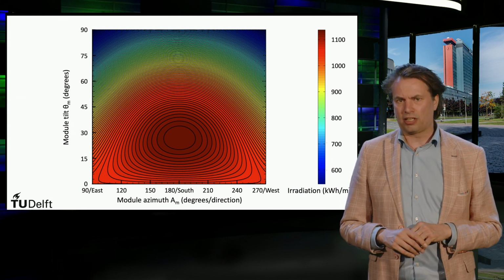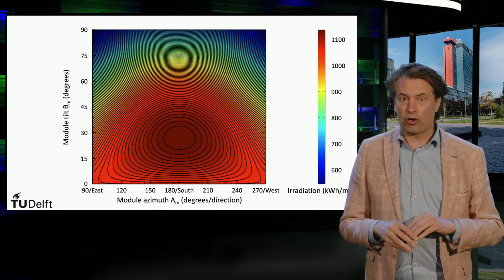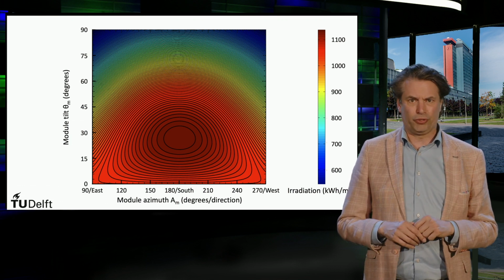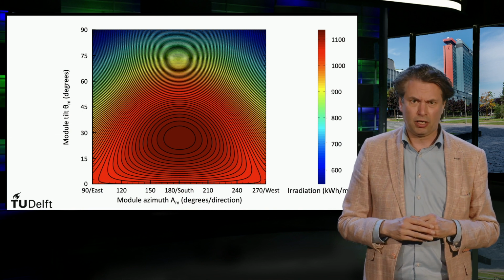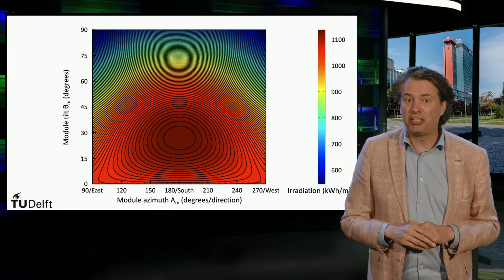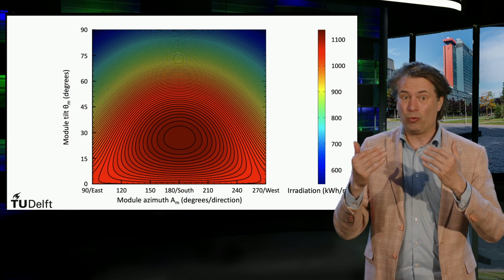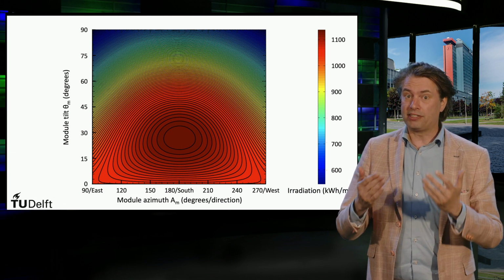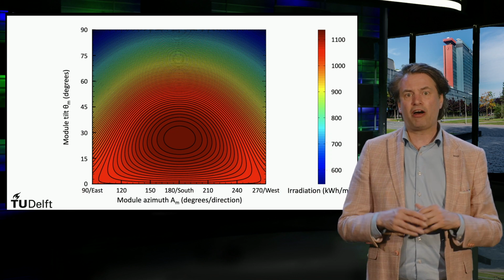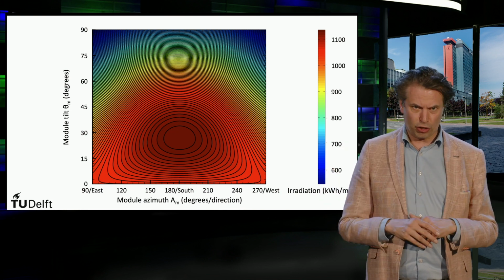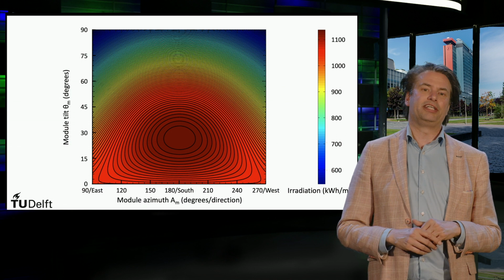Note that in some installations the array tilt angle or azimuth angle is decided for you. This can be the case for a sloped roof mounted system. Moreover, if your energy demand is highest in winter, then you can optimize the tilt and azimuth for the winter months. This will, however, inevitably lead to a suboptimal annual yield.